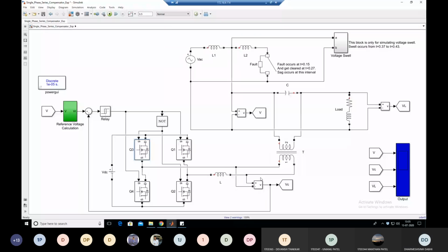And at the output side of this converter, we connect the series transformer, which connects the voltage in series with the line here. You can see that. This one is a positive terminal where we connect the inductor to limit the current. And here is the negative, or you can say the neutral wire. So there is a positive and neutral. Clear? So this is a positive terminal of the transformer. This is positive and this is negative.